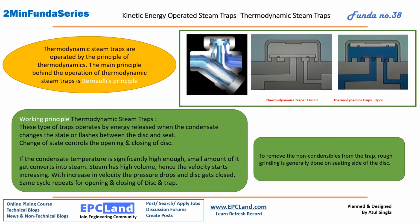Thermodynamic steam traps. These are the traps which work on the principle of thermodynamics, Bernoulli's principle. That is, with an increase in velocity, pressure decreases. These types of steam traps are also called disc type traps. This is a disc chamber where the volume is substantially high as compared to the inlet and outlet port. It operates based on the change in state of condensate to steam. So change of state controls the opening and closing of the disc. This is the basic principle.